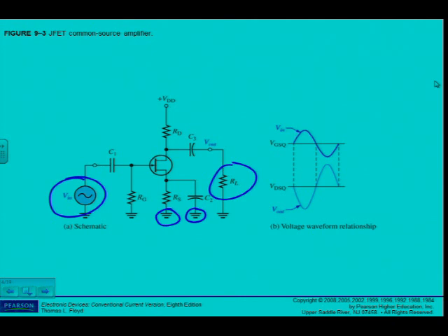Alright. Also, if I look at the input and output signals, as they are shown here, input signal, output signal, I can see it's amplified on the output, and also, the same as for the common emitter amplifier, it's 180 degrees out of phase as well. Alright, so let's refer back to the textbook so that you can mark what I've marked there.